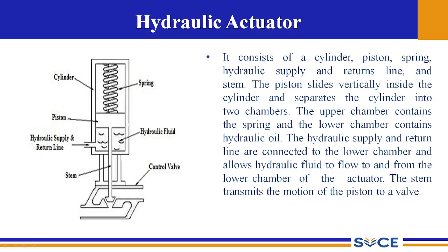The force exerted by this hydraulic fluid when moving up or down will be balanced by the force exerted on this spring, whether it is in tension or in compression. So the hydraulic fluid will be helping the piston to move up or down, so that the stem position will decide whether the valve is opened or closed. So this is the principle of the hydraulic actuator.